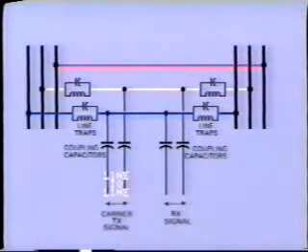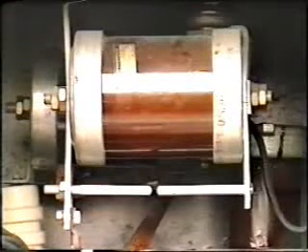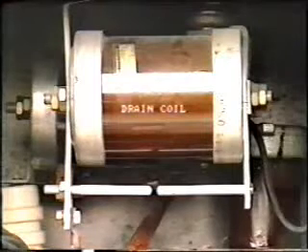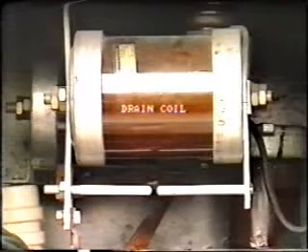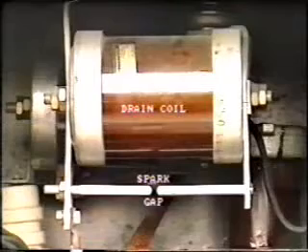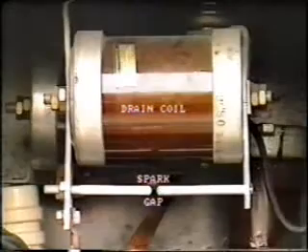The carrier signal is applied line to line. With this arrangement, the requirement for line coupling equipment is doubled. Let's get back to our carrier accessories as they are known. The drain coil is made of very light wire and therefore cannot withstand high current or survive high voltages such as lightning transients. This is why the lightning arrestor is installed here.